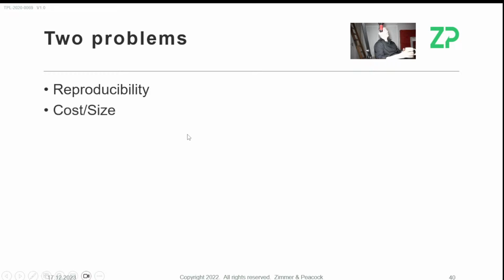The object that you're describing is quite large, and it has platinum on it and gold. Platinum and gold are expensive materials, so the materials themselves are going to give you a cost, and then the size of the device as well. So I will talk about a term that's not used very much, but I would call it manufacturing density. How many devices can I make per second? Because the larger you make this device, the fewer devices we can make per second, essentially. And then really quality, and quality does come from reproducibility.